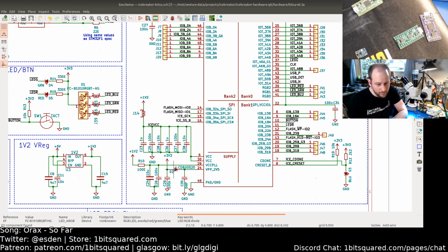But for some people that want to prototype a solution that uses NVCM and use the iCE40 as a single-use, specific-purpose device where they want to save money on the flash, this is an interesting solution, and it is important to provide that functionality on the dev board.